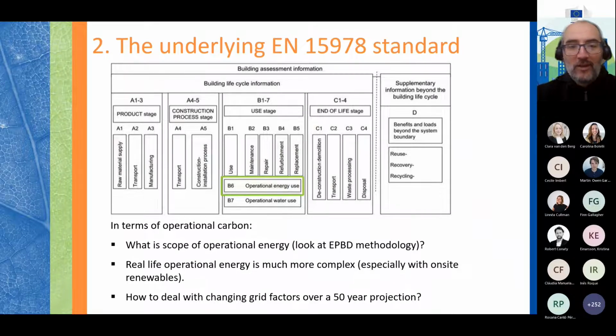So you have to be very careful how you define the scope of your operational energy, because it's just becoming more complex, especially for people who want to bring renewable energy systems on site to get this low carbon operational phase. It becomes even more complex because you have this added potential exporting and importing balance, because your on-site renewables are not always going to match your current needs. So imagine an office during the weekend with PV panels. They're going to be exporting potentially during the weekend and importing on a Monday morning when the sun's not shining so much. So really, it's important to get good estimates here.